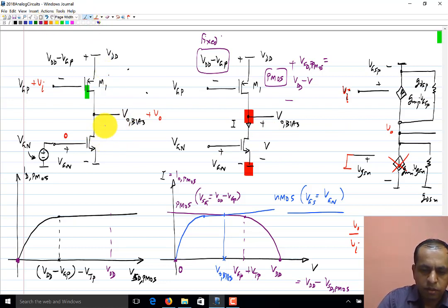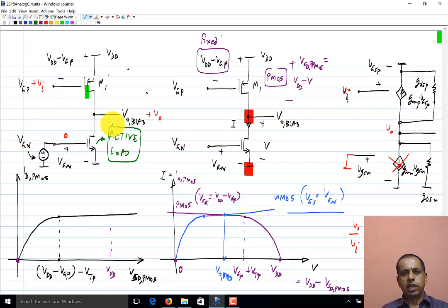Okay. So that's why this circuit is known as an active load circuit, or this MOS transistor here is the active load. Okay. We refer to transistors as active devices. I think you already know that they are not active in their total picture. They are passive because they draw power, but incrementally they can look like active devices. And frequently we use the output conductance of a transistor as a very large resistance which can be used as a load.